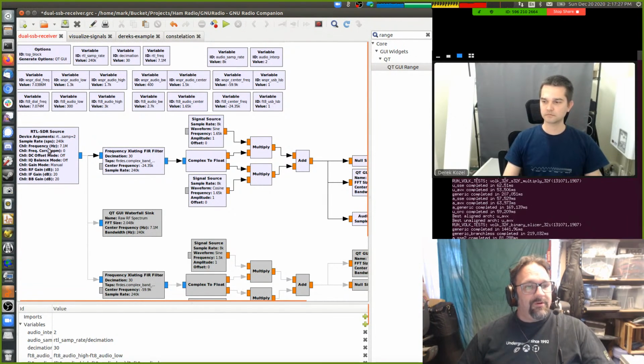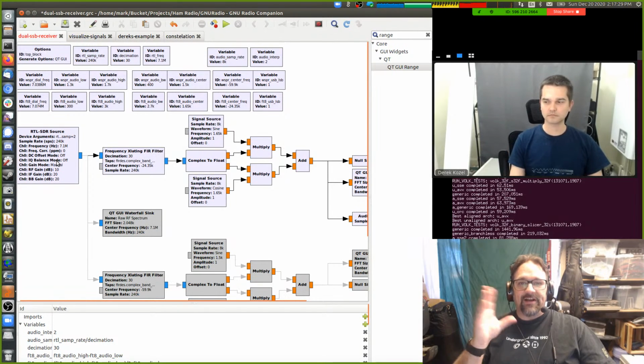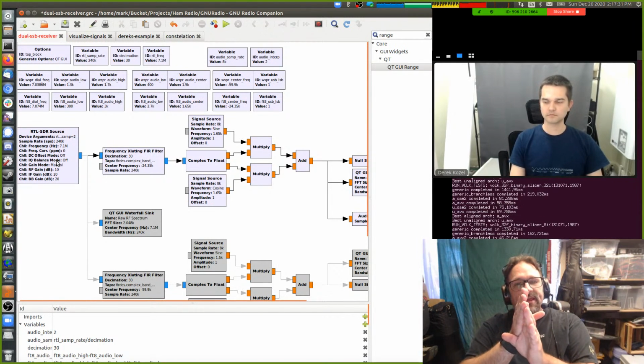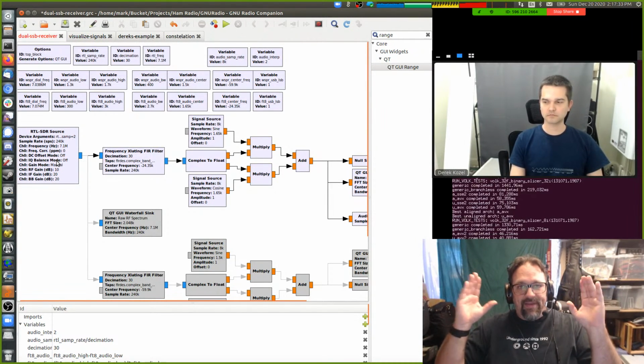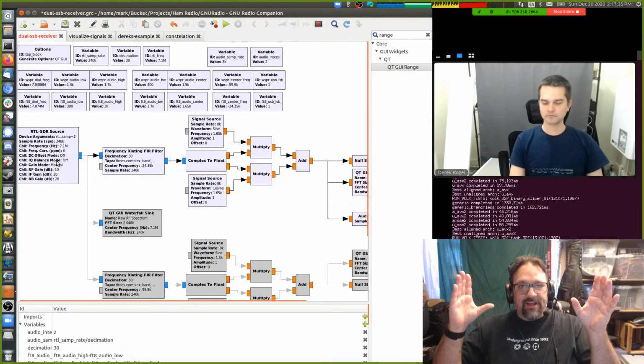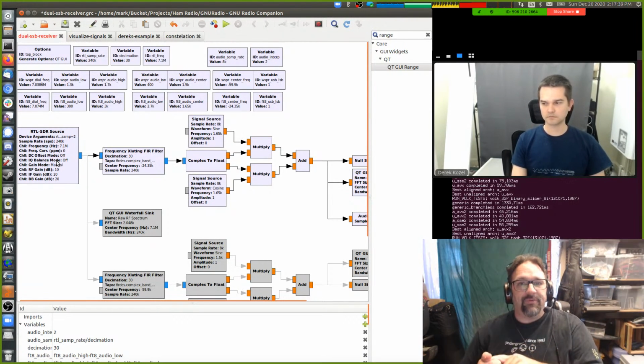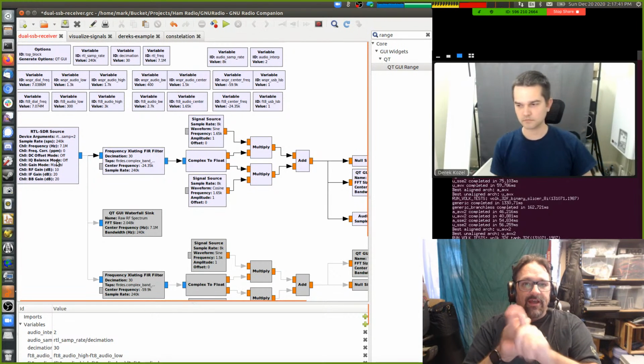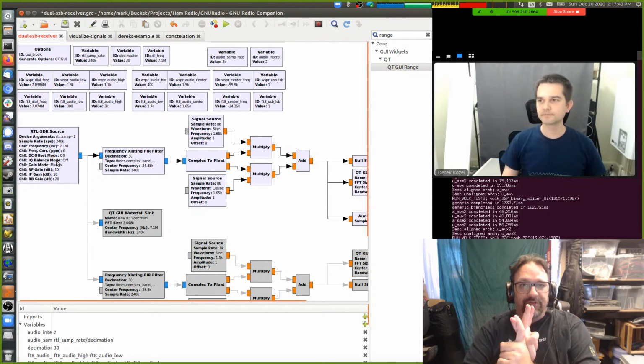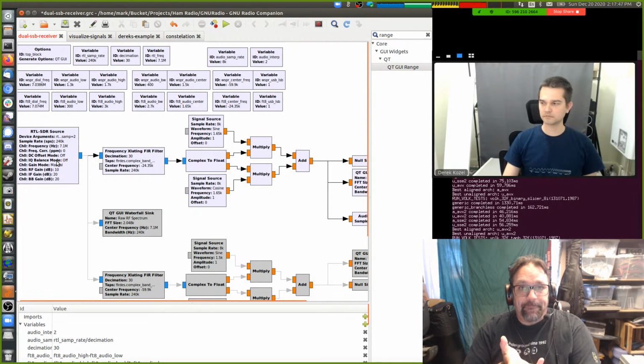Like when we were talking about where in the heterodyne path, like you picture a superheterodyne receiver, where in that path do you convert it to numbers? The RTL is already doing that first LO, that first mixer, and that first filter, and our first IF is where we are sampling, right?